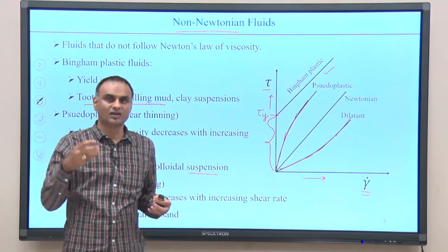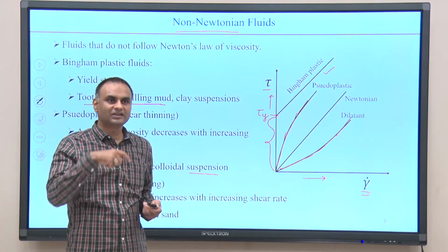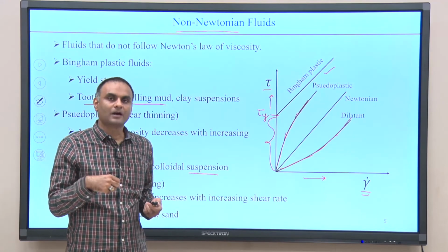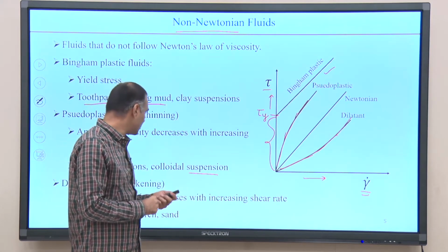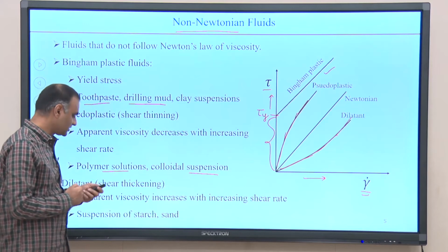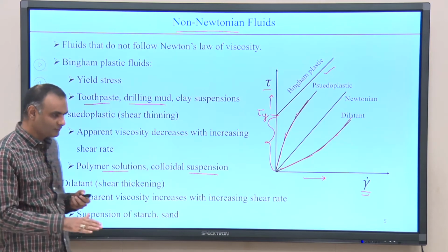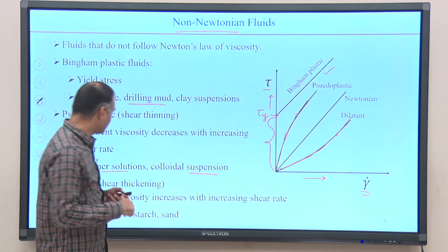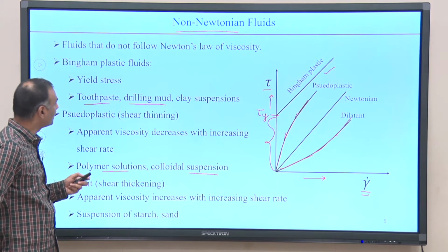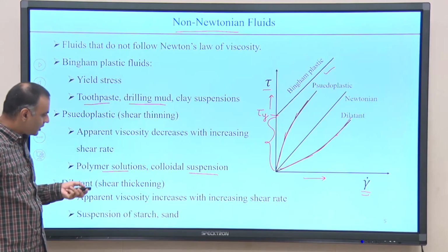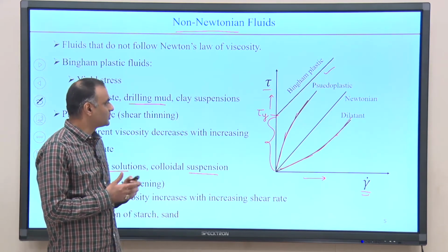If you take corn starch, put it in water and try to stir it, you will find that as you increase the speed of stirring, it gets harder and harder to stir, because the viscosity of the suspension keeps increasing with an increase in shear rate. The same is true with sand, and you can experience it when you walk on a beach. When you press it, you find it more difficult to apply the shear stress. So, these are some common examples of non-Newtonian fluids. All of these non-Newtonian fluids are time independent fluids. That means their behavior does not depend on time.